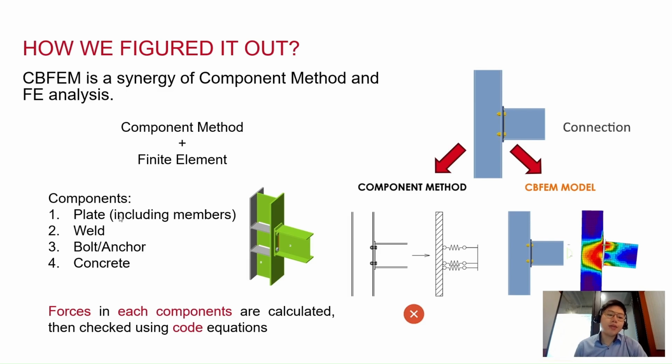Number one will be plate, which includes the members like this I members here. And then the second one will be weld, bolt or anchor, and the last one will be concrete. Then after the CBFEM analysis is run, the forces of each element will be checked against the code equation.